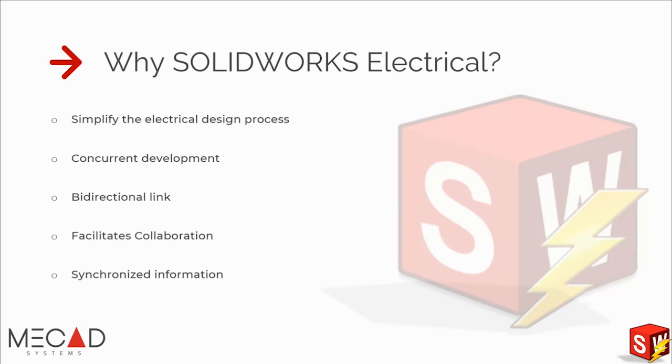SOLIDWORKS Electrical also translates single-line schematics into detailed multi-line power, control and PLC schematics. It also offers a detailed terminal strip management tool, which is actually one of the nice features in SOLIDWORKS Electrical. And lastly, it allows for the reuse of existing designs. So no more do you have to redesign, for example, a direct online starter. You don't have to continually start with each and every component. It's just a matter of creating macros of a circuit and copying and reusing that information.